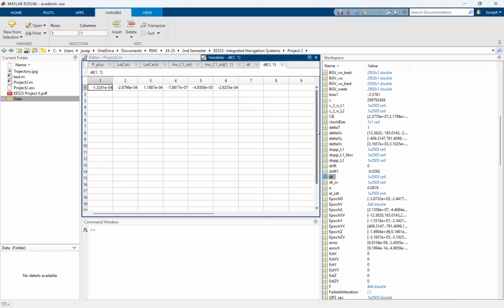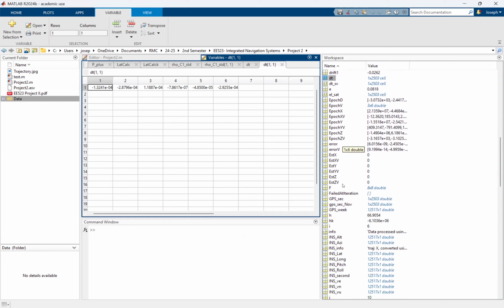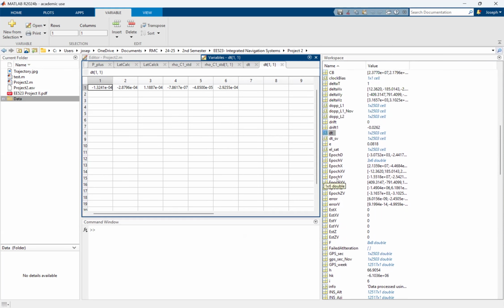For calculating R with the Kalman filter, I don't see anything in the data set related to the Doppler standard deviation. I only see the range. So at least in your example, we get calculated R from the position, right? Not the velocity. So we feed the Kalman filter the standard deviations of the positions, that's the standard deviation of latitude, longitude, and altitude. You will see them somewhere.